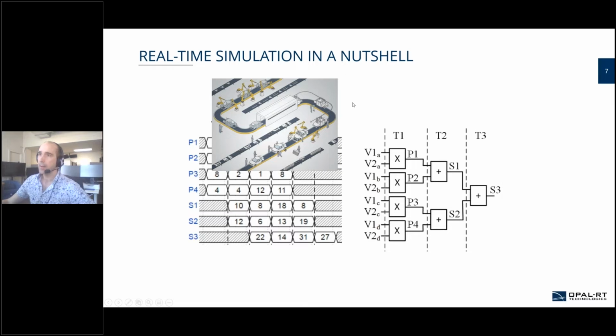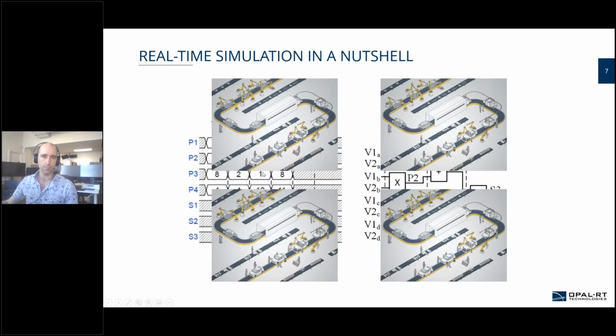So you can think of it like an assembly line. It takes maybe 1 day to build the car, but you have a car coming out every second. And then once you have one assembly line that works well on the FPGA, you can just put many in parallel to increase the computation power. So this is the main reason why we achieve such a small time step in FPGA: although the clock of the FPGA is much slower than the clock of a CPU, everything that is designed on FPGA is specially designed to be extremely efficient for the thing that you want to do.